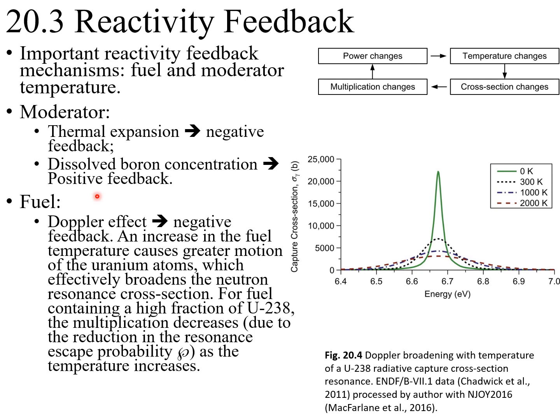In general, if the reactor is over-moderated, you have more water per fuel pin, and the moderator temperature feedback is positive. If your reactor is designed to be under-moderated, the moderator temperature feedback will be negative. Therefore, for commercial reactors, we normally design the core to be under-moderated.